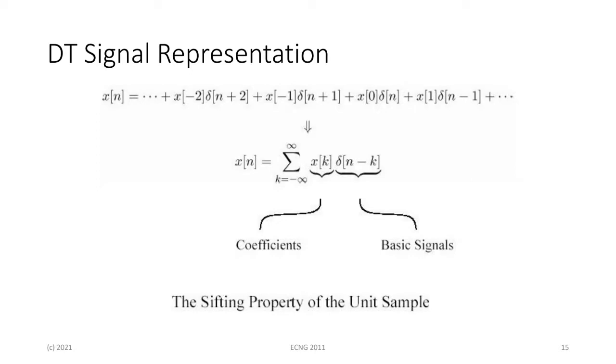And this is just a summary of what we just said. This is the reverse of what we just spoke about. So you take a signal, you sample it, and you have a series of samples. What this is telling me is that I could take those samples, which are now tangible values, and break them up as a sum, in shorthand, of individual impulses all over the place. Make sense? Good.